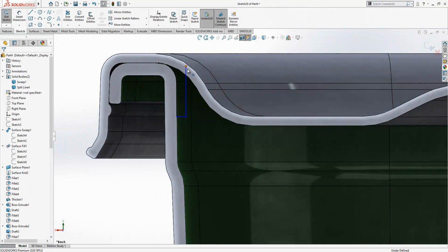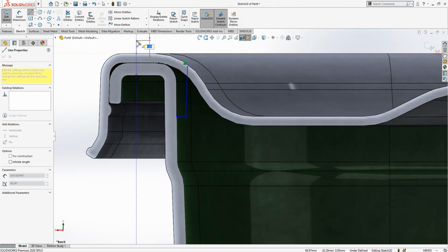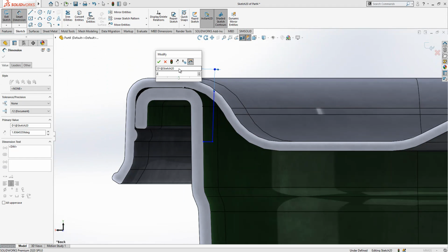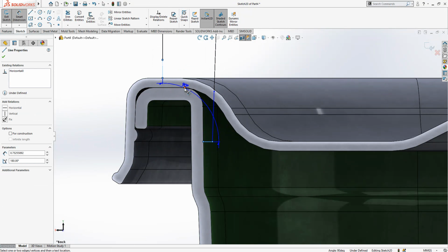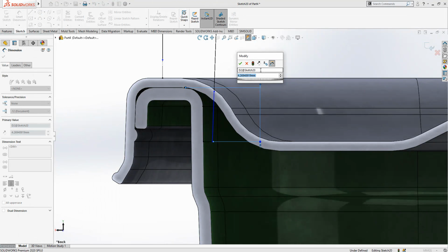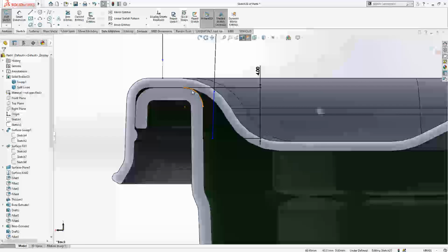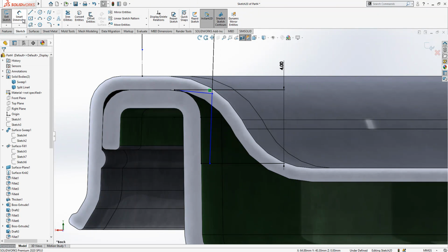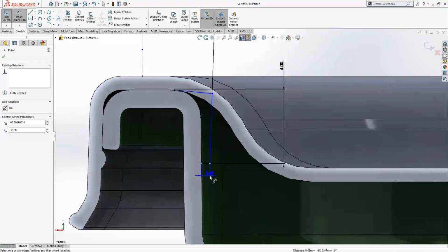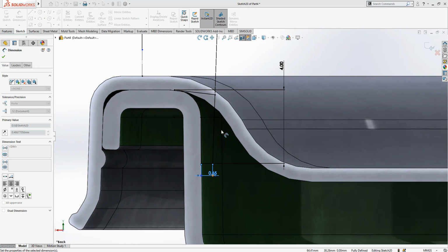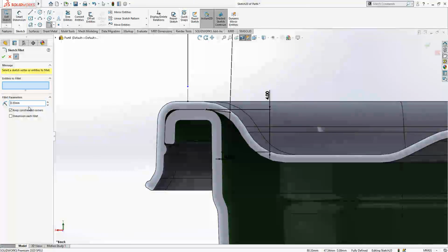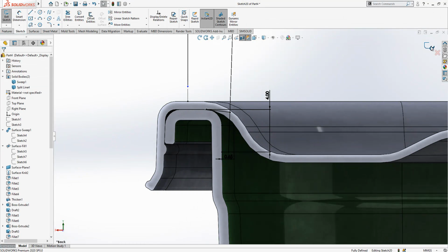Shouldn't be a straight line. Everything should have some angle, otherwise it will be difficult to remove them from mold. 2. And 4 is alright. And then we can hide them, something like this, and then the value will be 0.65. Yes, it is good. It's a form again, and then we are going to create a radius, but we can do that after as well.